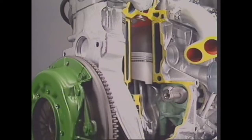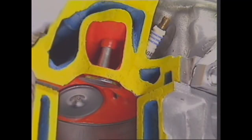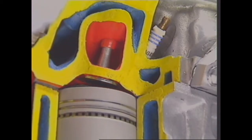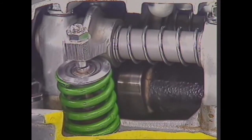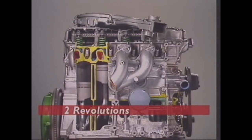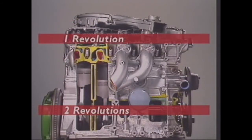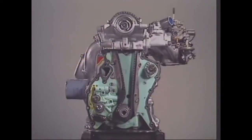Twice. It makes 2 revolutions. During that time, what happens to the valves? They open and close once. So the cams must turn through just 1 revolution, as does the camshaft. In each cycle, the crankshaft turns twice and the camshaft only once. So the camshaft must turn at half the speed of the crankshaft.